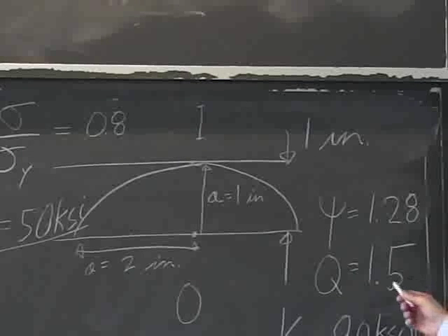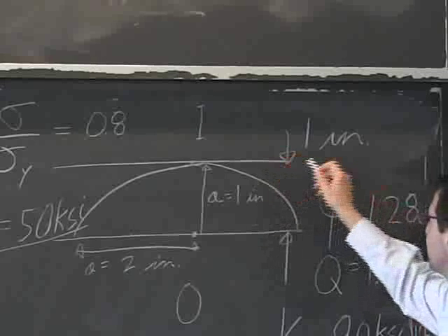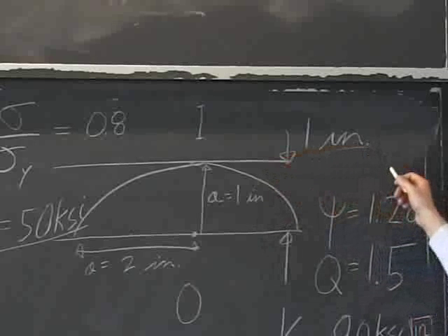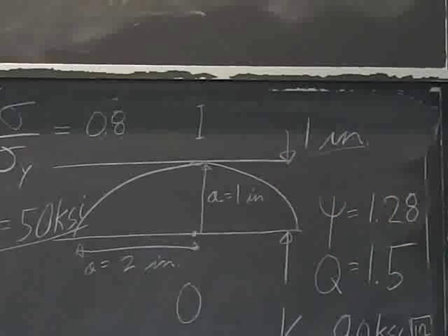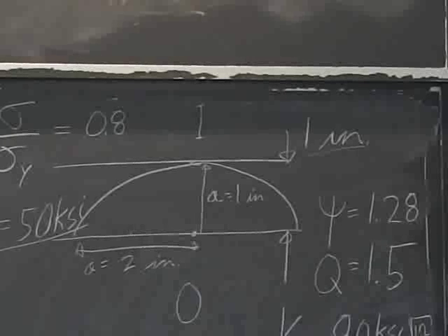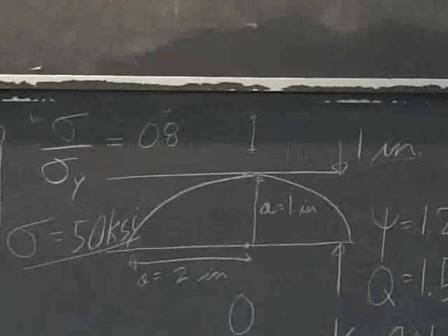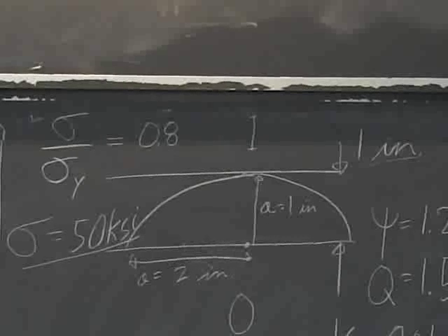So all we did really is we said, okay, this is my thickness, and then went all the way through to, well, this is the fracture toughness I need if I want to be able to grow the crack and not have it pop on me, leading to overload final fracture. You can do it the other way around. Another case I did was a milder steel.